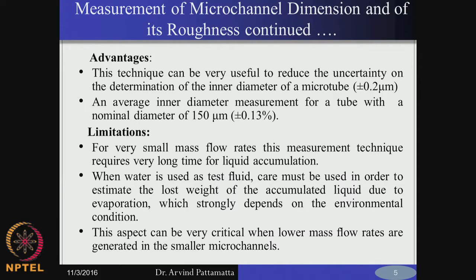Okay. And again, depending on the working fluid, you assume that there is no evaporation, that this is an adiabatic case, but in reality, if you use water for example, depending on the surrounding humidity, there could be some losses due to evaporation. In that case, there will be some water vapor that could be accumulated inside, or there could be loss of water.